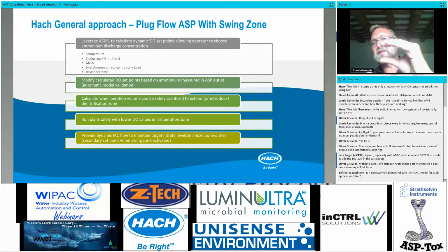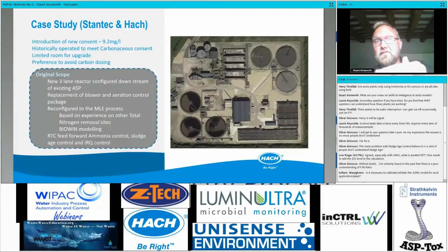By switching from a kilograms per hour or a treatment rate, which is not something that operators carry in their head, to just whether the resultant sacrifice of volume still allows us to safely operate within the operational window that you set, that is a much more meaningful way for the customers to optimize the system and to parameterize it in a way that's acceptable to them.